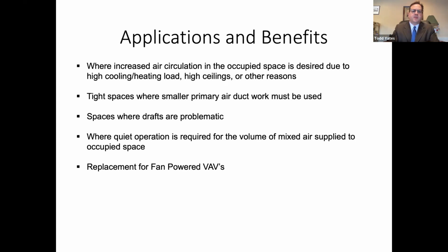These are also used where quiet operation is required in the occupied space if noise levels are a concern. And in some instances, they can be used to replace fan-powered VAVs because they can mix that plenum air before it gets to the occupant areas.